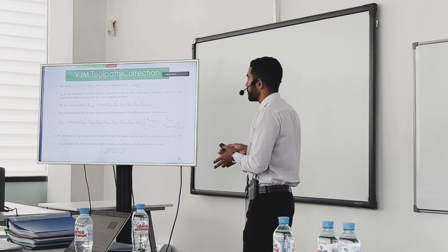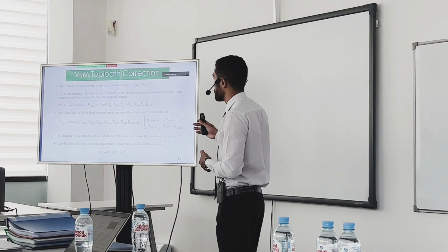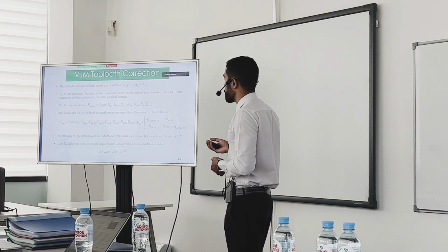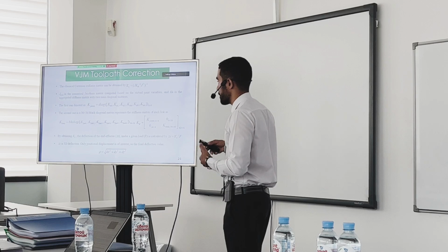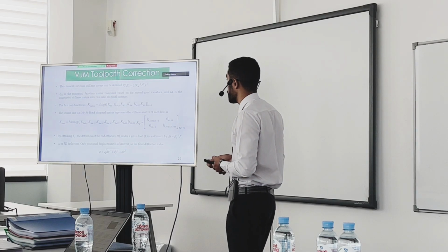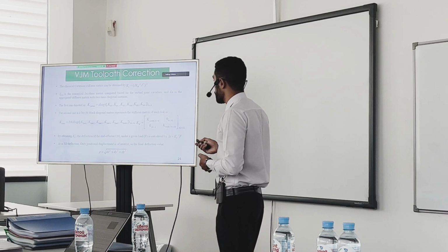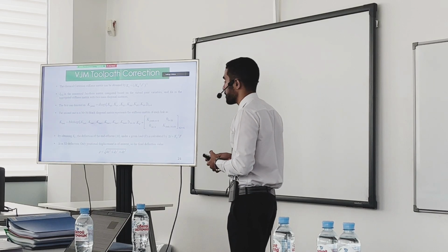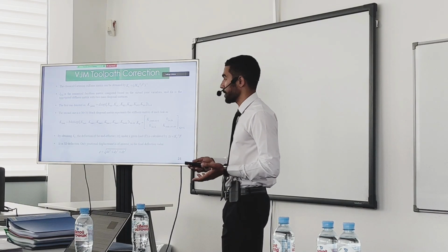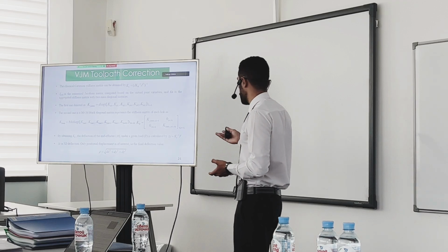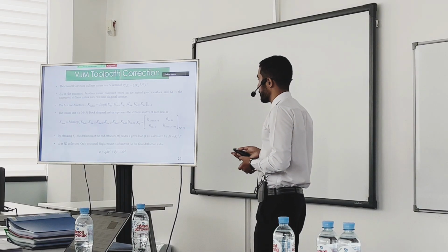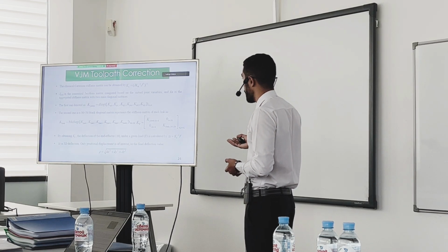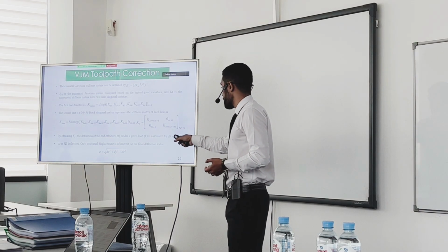So the basic idea behind the VJM is to obtain the classical Cartesian stiffness matrix, which can be obtained out of the Jacobian matrix, and here it's computed numerically. It's worth mentioning that this K theta is the aggregated matrix that combines the stiffness matrices of the joints and the stiffness matrices of the links. It will be of size 42, because we have 42 virtual springs, and the principal idea behind this is Hooke's law in simple words.